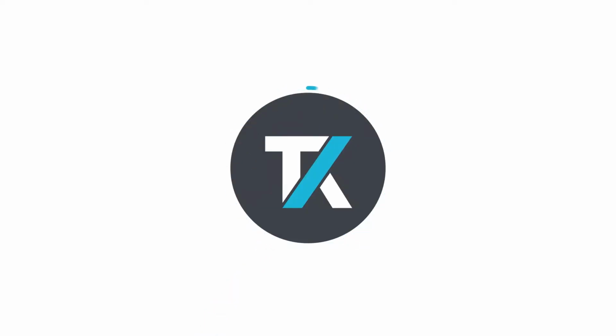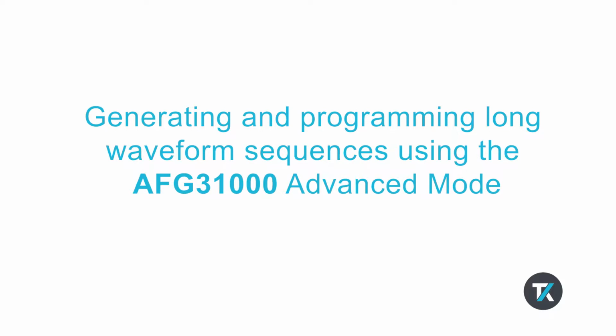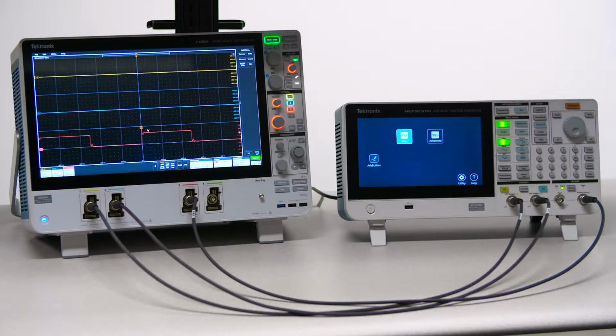If you need to generate long waveforms or waveforms with complex timing, like pulse trains or data packets in a serial bus, choose Advanced Mode. In this demo, I'll show you how to program a simple waveform sequence in 3 entries and how to change the way they are played out.